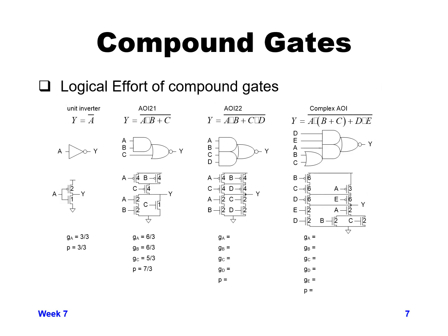Now that you know a little bit of the basics of creating more compound gates and more complex compound gates, let's go into computing the logical effort of compound gates as opposed to the simple gates that we've done so far. Just as a review, the unit inverter is just an inverting function, and that is the basis of our unit delay.